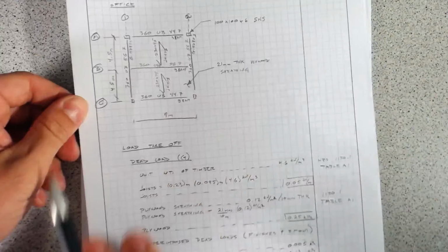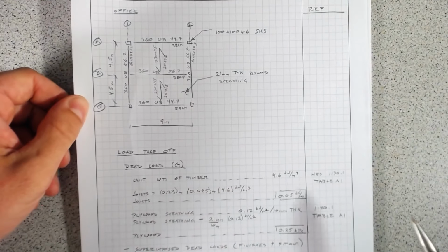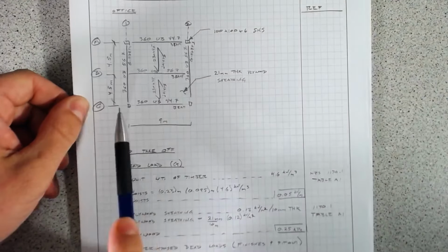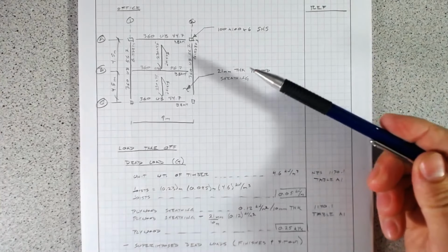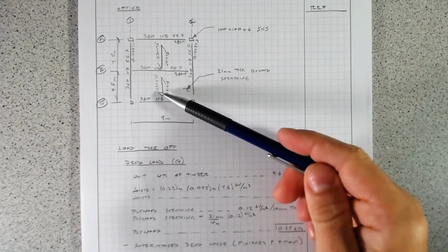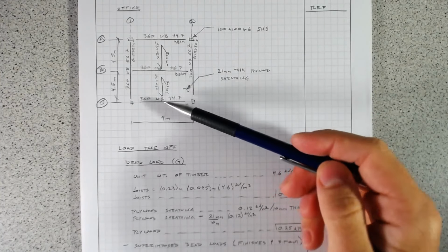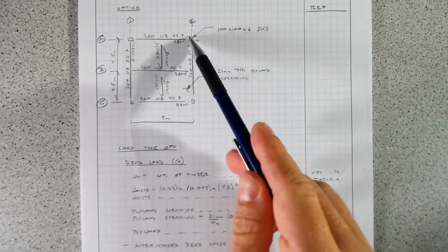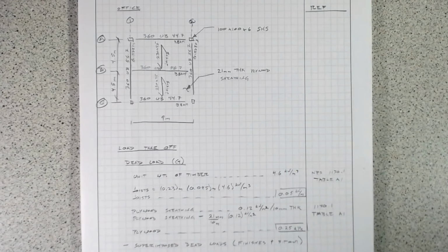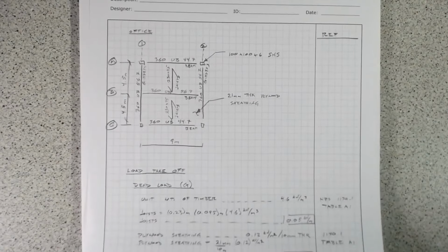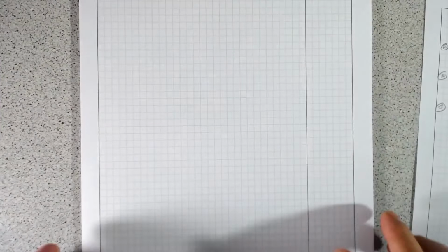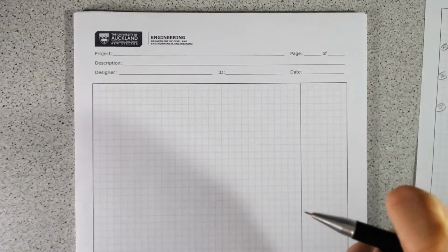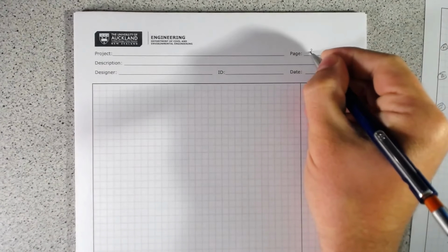So now that we have all of the loads, and we see the joist spanning this way, what we want to do is chase the loads from the plywood sheathing to the joists, to the beams, and then to the girders, and then into each of the columns. So that's what we're going to step through here. We're going to just work through, and this is, as I said, very similar to what you would do for calculating these loads for a building.